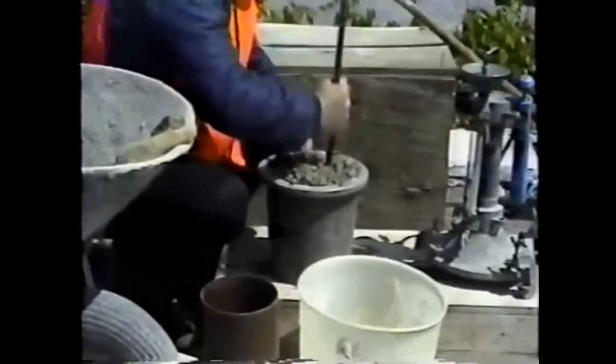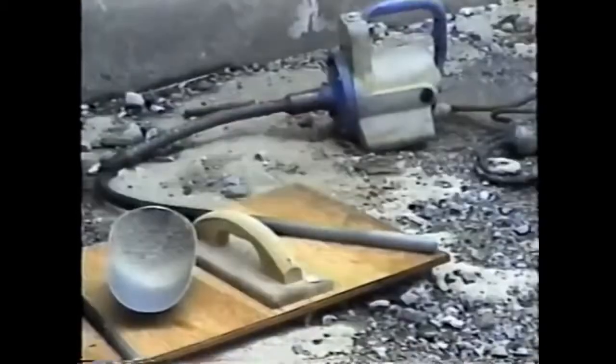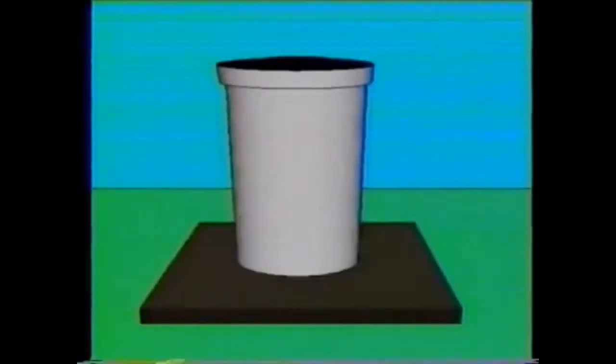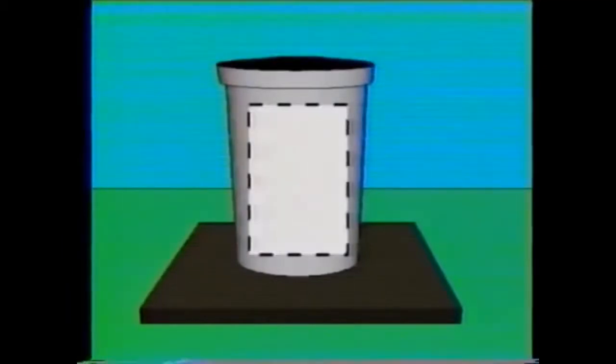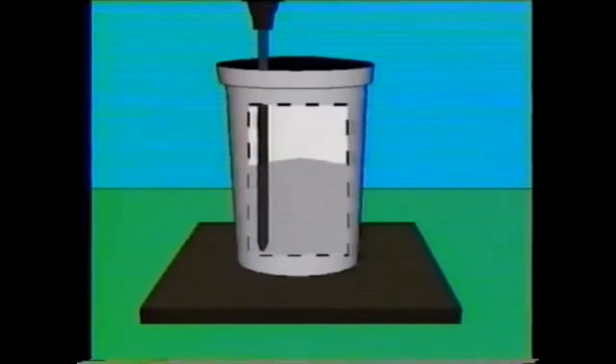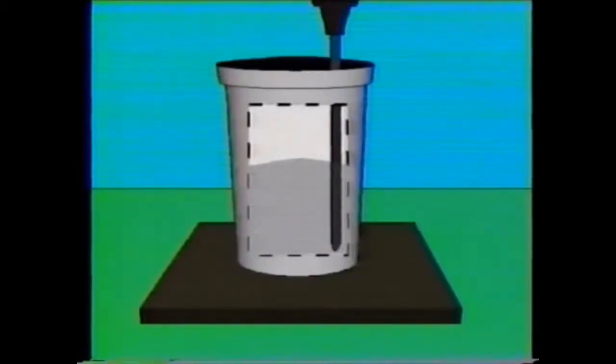The final layer of concrete is added without excessively overfilling the bowl. When the vibrator is used, the bowl should be filled in 2 layers of approximately equal volume. After the first layer is added, the vibrator is inserted 3 times at points evenly distributed over the cross-section. The vibrator must not touch or rest on the bottom or sides of the bowl, and the concrete should not be over-vibrated. Such practices segregate the aggregate and lose some of the intentionally entrained air.